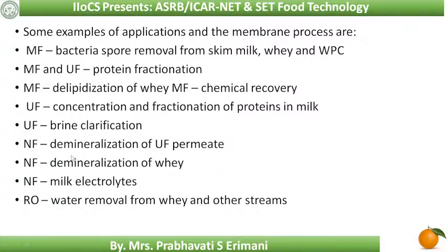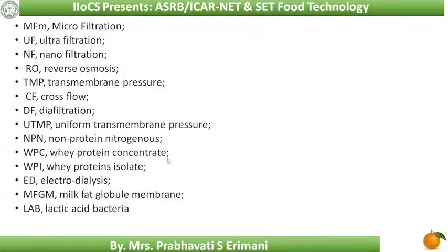Nanofiltration for demineralization of the ultrafiltration permeate. Nanofiltration again for demineralization of the whey, and for milk electrolytes. Reverse osmosis is for the water removal from the whey and other streams. Since more water will be there in the whey, it can be removed by means of reverse osmosis. So these are some of the applications.